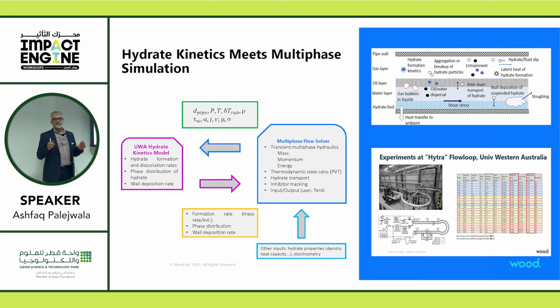So this is really an integrated solution where you have an independent, I suppose, DLL or algorithm that looks at the kinetics, and then you have a multiphase simulation solver which puts the process data back into the model, and it keeps going round and round. With this, you look at the formation rate, see how the formation rate affects the thermodynamics, and see how the thermodynamics affects the formation rate. So really that's the heart of the research.